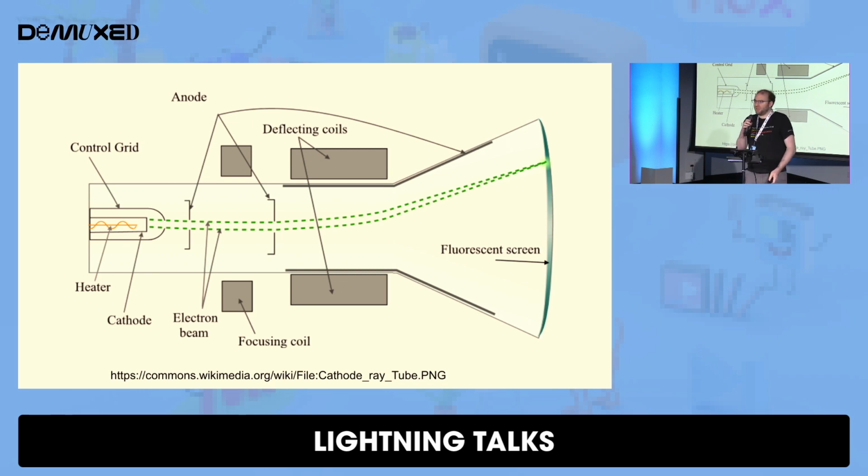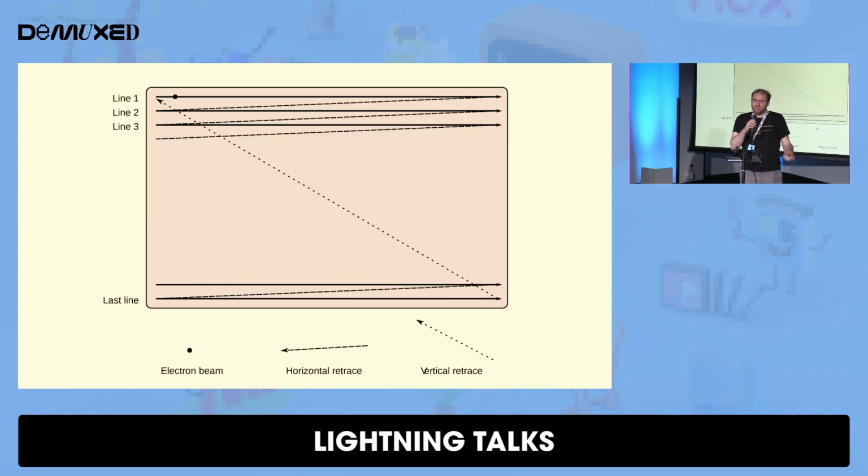So how do we aim it on the screen? Well, you all know that video basically goes left to right, top to bottom. You store the pixels in a buffer. But before that, when we had analog TV, we scanned it in the same order. So the whole idea here is that on, like, a VGA connector, whatever the red, green, and blue is on there is directly what's sent to the CRT's cathodes. It's displaying the exact color at any moment in time that is presented to it.